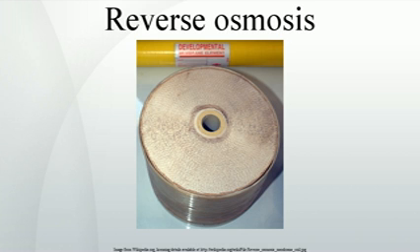The typical single-pass seawater reverse osmosis system consists of intake, pretreatment, high-pressure pump, if not combined with energy recovery, membrane assembly, energy recovery, if used, remineralization and pH adjustment, disinfection, alarm control panel.